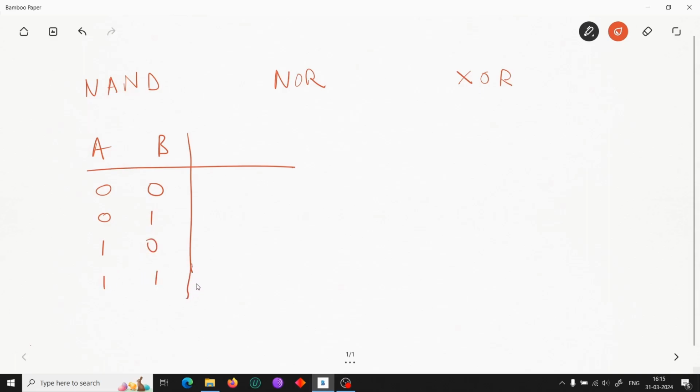Remember the alternate circuit that I was talking about? Well, people actually have come up with that and designed that circuit as well, and they are basically these gates. So a NAND operator is basically the same as the AND operator, but the output is complemented. So when both values are 0, the output is 1, and when any one of them is present, then also the output is 1, and finally when both are 1, the output is 0.